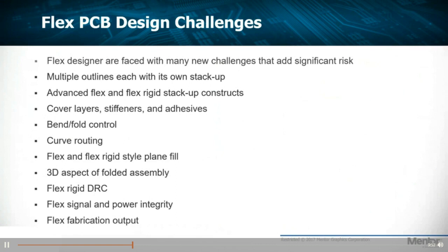The stack-up in a rigid flex design is very unique compared to just a rigid design. You do have to define certain layers in only certain areas of the board, and that can be a very big challenge that is tackled quite well in PADS Professional. Some of these layers include cover layers, stiffeners, and adhesives. And again, these are all unique to rigid flex designs.